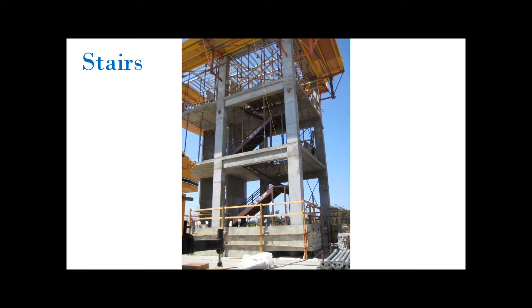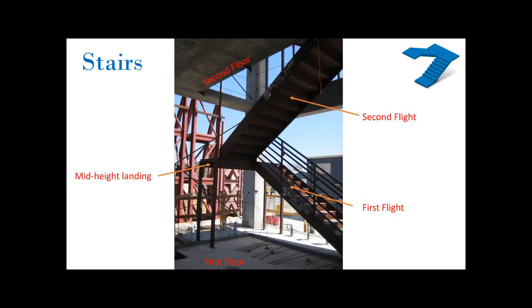In the 5-story building test, prefabricated metal scissor stairs were used. In this particular scissor arrangement, 2 flights and 1 mid-height landing per floor formed the floor-to-floor stair assembly. These stairs, also referred to as half-landing stairs, reduce the quantity of treads in one flight and make walking more comfortable. Because they are very functional, safe, and most importantly compact in space, scissor stairs are used quite commonly.